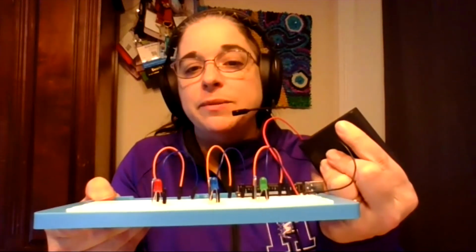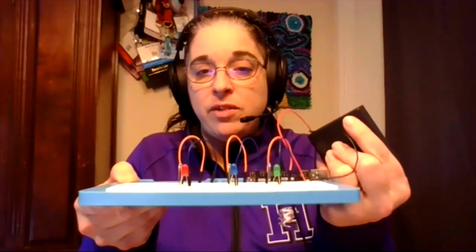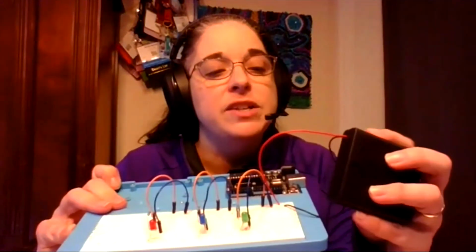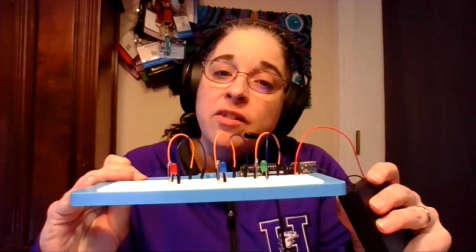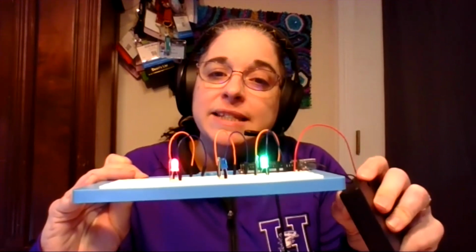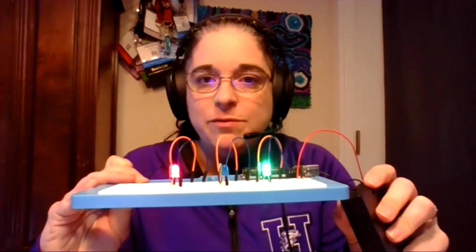What's super cool about this one is that I have it done as a parallel circuit. By parallel, I mean each LED is receiving current directly from our battery pack, rather than in a series circuit, where each one would be drawing its power from the next. Because these are in parallel, just because one of my lights is not working doesn't make all the rest of my lights cut off.